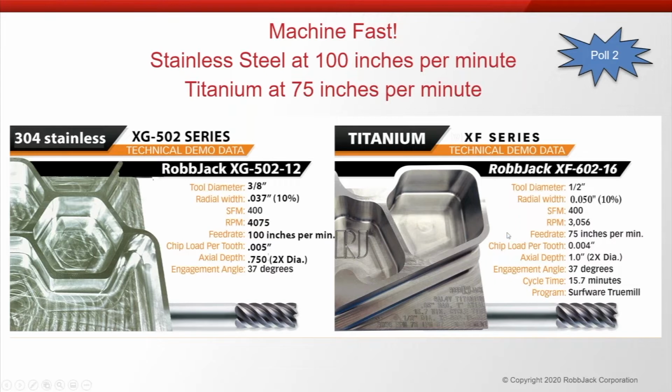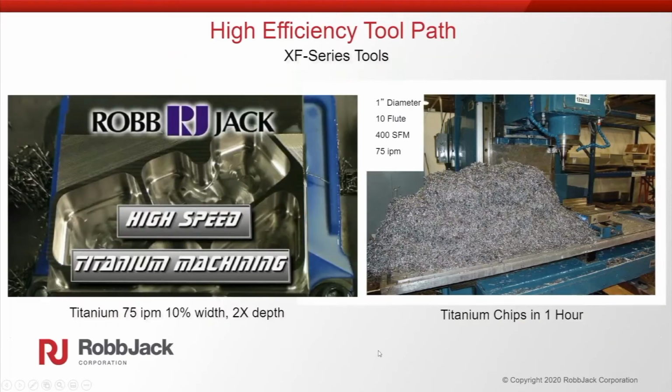And we're going to show a titanium part in just a minute. It's the same thing, this is with a 1/2 inch tool going 10% step over, which is 50 thousandths, but 1 inch deep in a single pass. So here's a video of a part done that way.